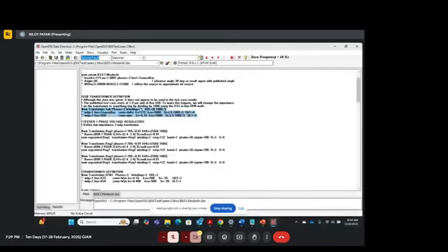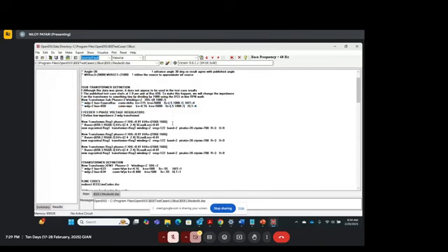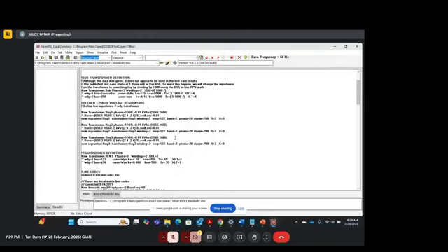It has 2 windings, it has 3 phases, and it connects the source bus to bus 650. The source bus is on the delta side. The 650 node is on the Y connection, and then you have kV levels, and R and X values are put exactly. You have to match that with the doc file.